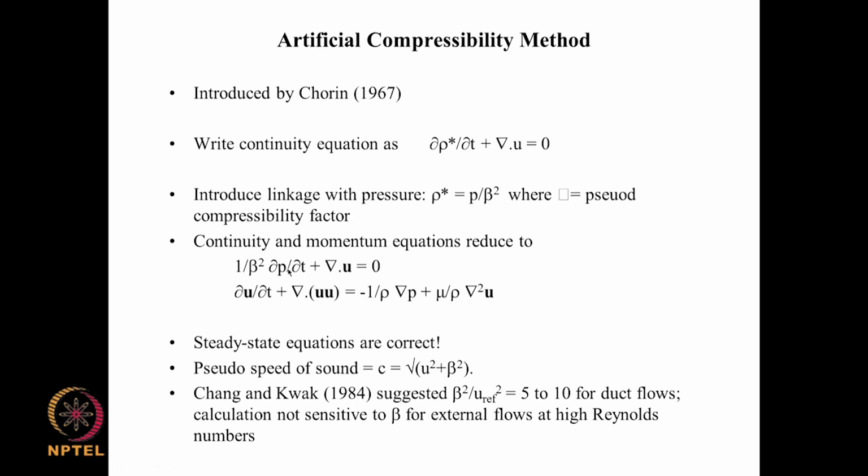We solve the continuity equation for P. It is like the previous continuity equation where you have density variation ∂ρ/∂t. In a similar way, we can solve this equation for P, or solve it for ρ*, and then once we have ρ*, we can get P, provided we have β. Then we substitute that P into the momentum equation for u, the x momentum or y momentum equation, in which pressure is no longer an unknown. It is already deduced from your continuity equation.